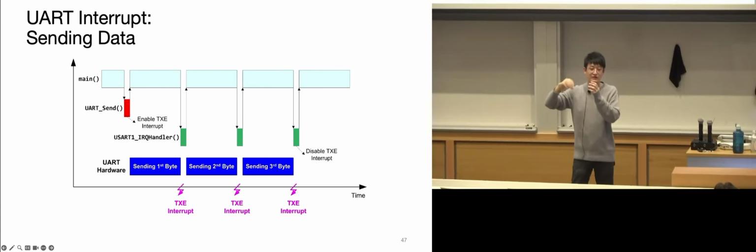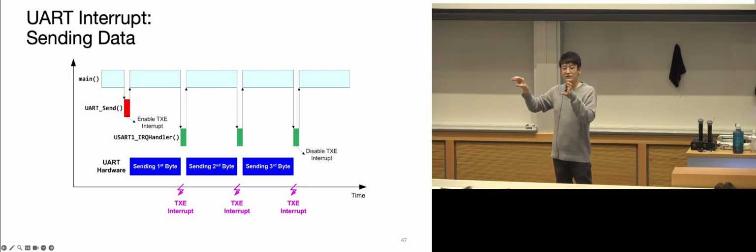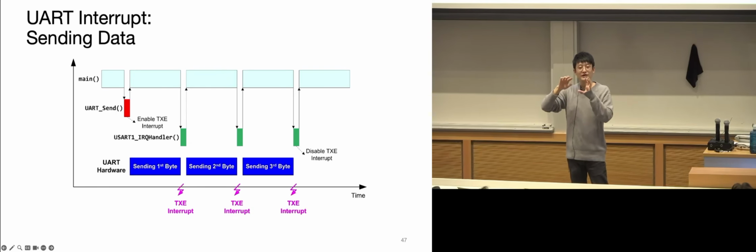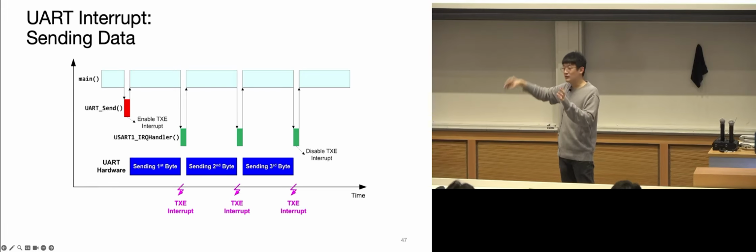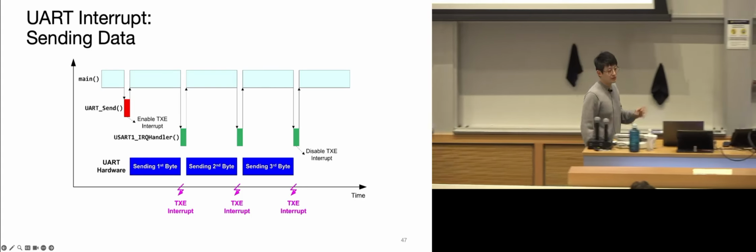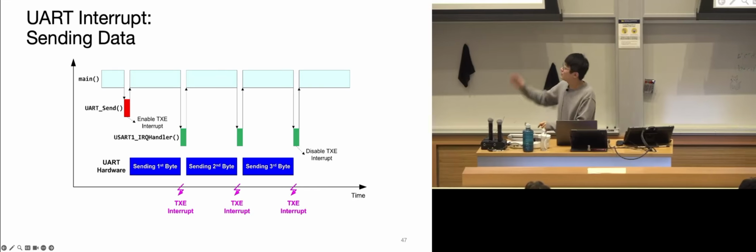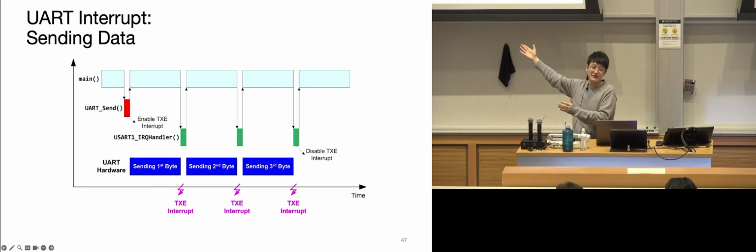It doesn't do unstacking, so it just does a bunch of interrupt handler calls for that one interrupt. And then once you finish that string of sending, it goes back to the normal processing mode, thread mode. It might look like a lot, but in real life, this takes a very small amount of time, which is also why you shouldn't send essays in any of these. You should send something quick, some strings, numbers. Don't send essays.